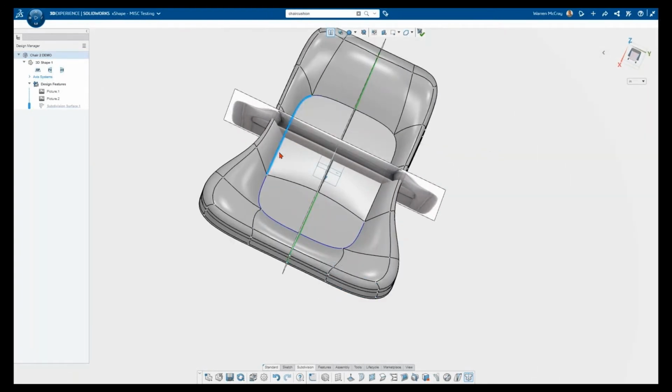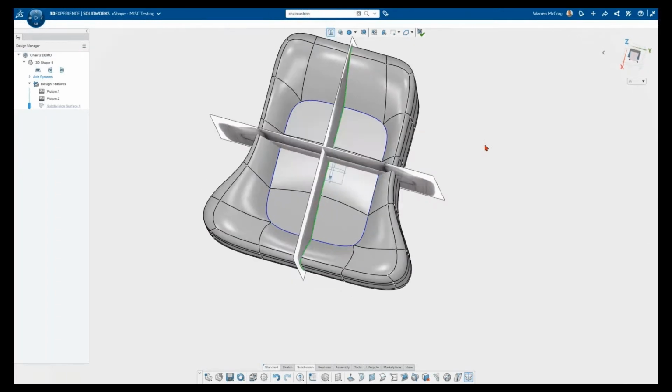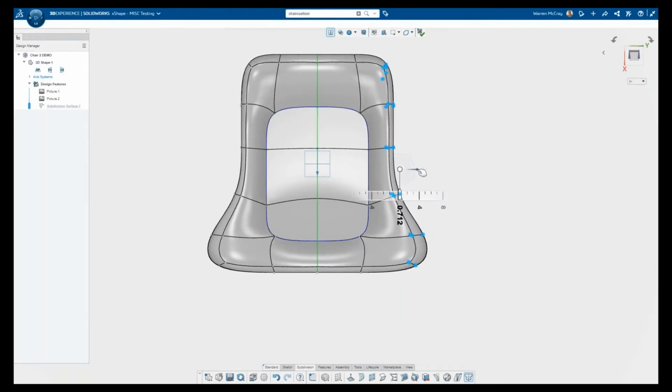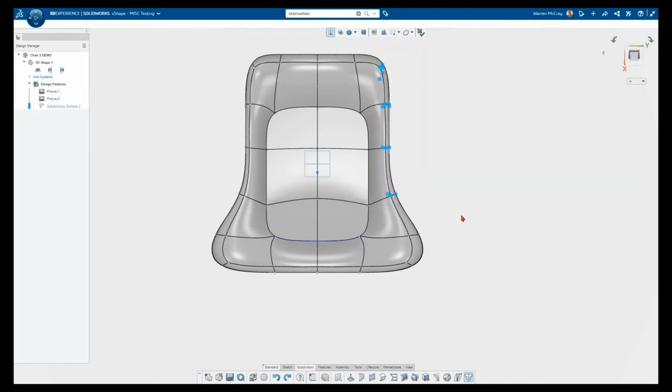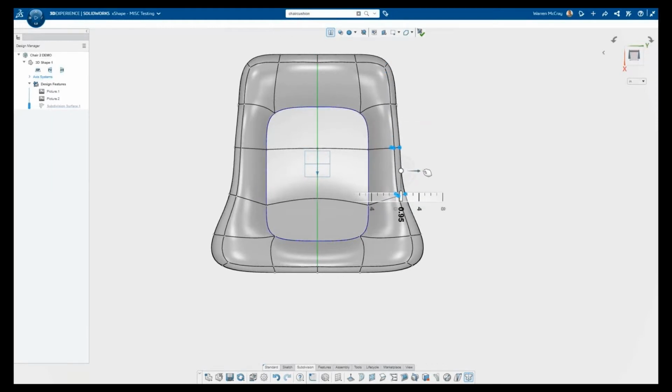That looked okay. So I'm going to go ahead and see if I can adjust this a little bit more. I'm trying to make it wider so that the material won't crease if it's too vertical. I'm trying to make it narrower on the bottom so that when I drag it down, the material doesn't fold on me. So I'm pulling it out, just window select these points, pull it out a little bit. And in this case, it pulled out everything. So what I'm going to do this time, I'll drag less entities and get a more refined surface.